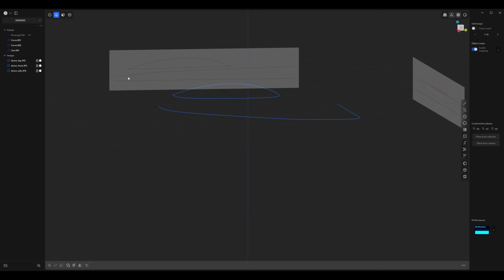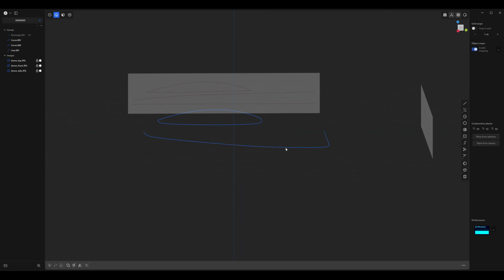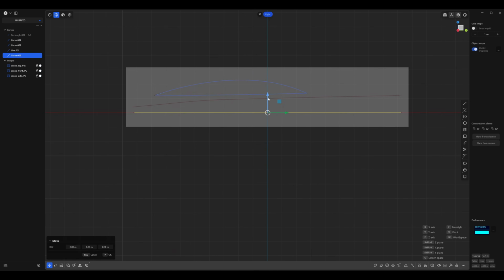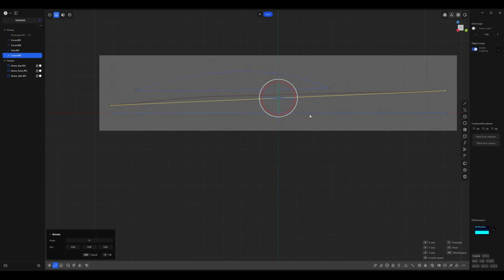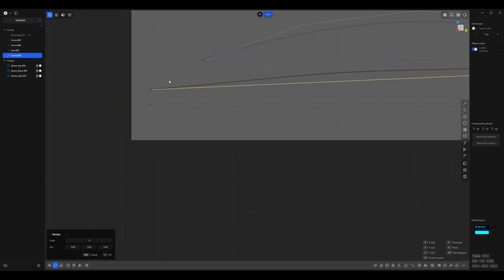The next thing is we need to define this kind of angled shape. So go ahead and select this bottom, go to the right view, press Shift D, and let's move it upwards. And again, you'll notice it's at an angle, so let's press R, and then press F to freestyle rotate as well. Click on the first end point and then the last end point. And let's kind of rotate it this way. And then press 1, just like we did with the canopy, so that we can adjust these points to match.